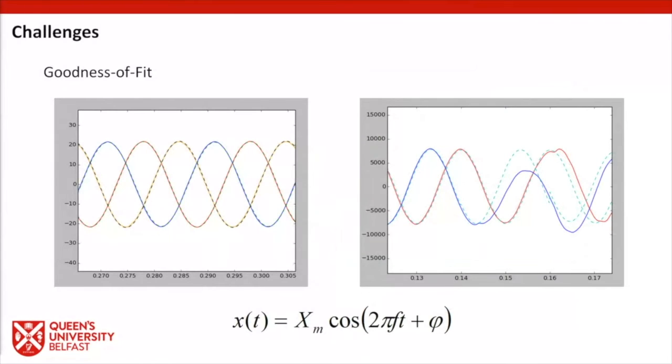What are some of the challenges which exist in terms of measuring the distribution network? Well, as I alluded to, one of the big problems that we have is that synchrophasors only describe AC waveforms. That is, that the waveform must be continuous, it must be time invariant. Strictly speaking, the mathematical definition says that it must be totally time invariant from t equals minus infinity to t equals plus infinity.